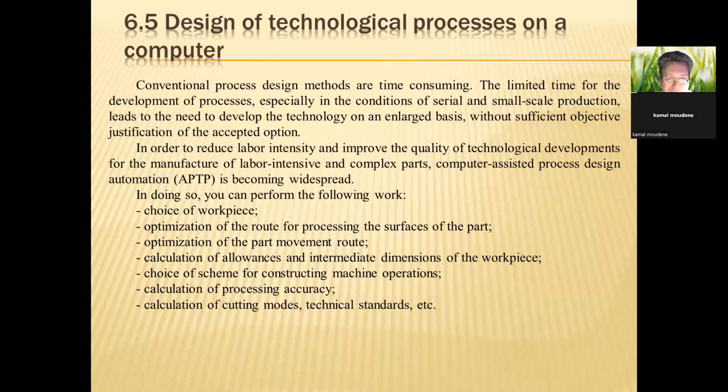In doing so, you can perform the following work: choice of workpiece, optimization of the route for processing the surfaces of the part, optimization of the part movement route, calculation of allowances and intermediate dimensions of the workpiece, choice of scheme for constructing machine operations, calculation of processing accuracy, calculation of cutting modes, technical standards, etc.